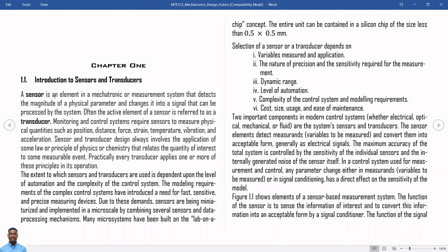So when the sensor detects the magnitude of the physical parameter, it changes that detection into an equivalent change in voltage level from its own output to the microcontroller, or current output from itself to the microcontroller. So the microcontroller now can read that voltage or current level to say, okay, this is the magnitude of what has been detected by the sensor.